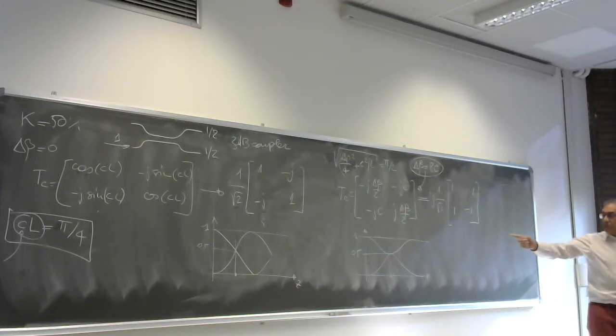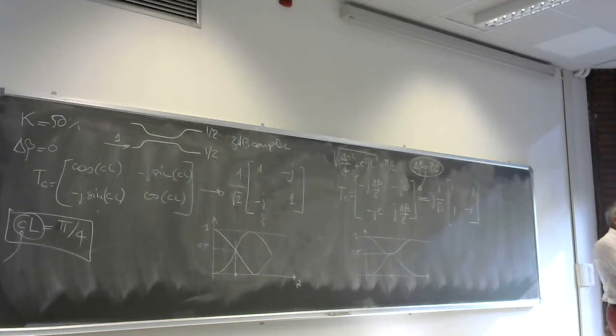You say that one because the two waveguides are equal. And what is the advantage of having the two waveguides equal? You say it's a cascading, you know the phase when you cascade. So you don't have to change the dimension of the waveguide. So you avoid the taper, you avoid the change of width. This is a good reason. This is why people use that solution.